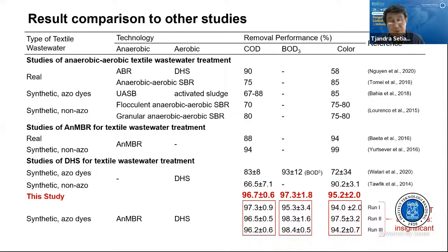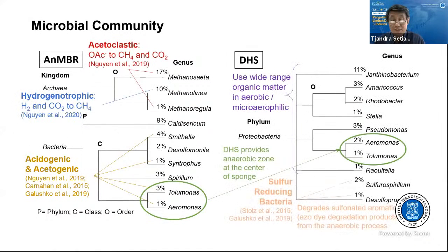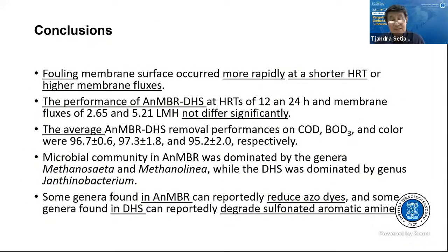Although the anaerobic membrane has been a challenge, I will skip the microbe part. So the conclusion is the fouling in the membranes is relatively rapid, especially at higher membrane fluxes. But the performance, even with the HRT of 12 hours, is very good.